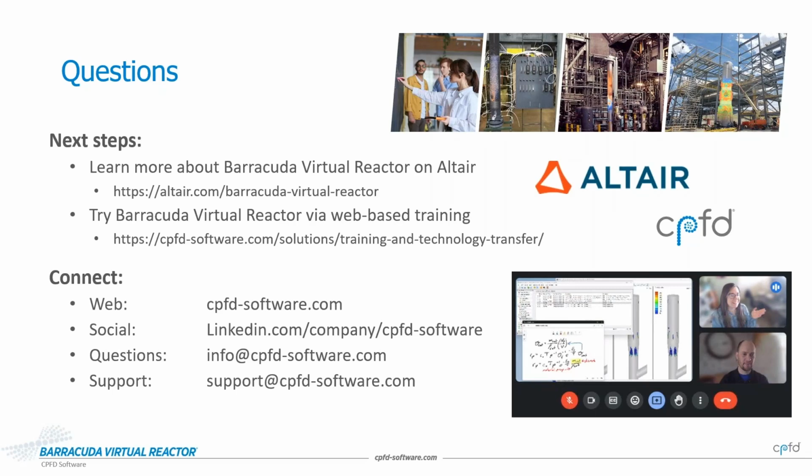Okay. And what are the models used for solving the gas or liquid phase and the solid particle phase? Is it a two-way coupled model? Okay, so the gas is Eulerian, the particles are Lagrangian, and they are bidirectionally coupled. So it's the gas or the fluid that would drag the particles. At the same time, those particles are occupying a volume and affecting the pressure drop in the fluid.